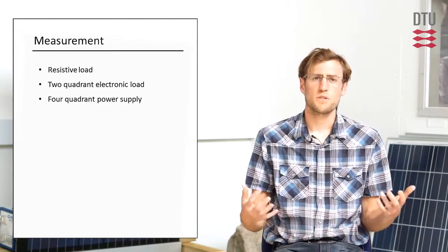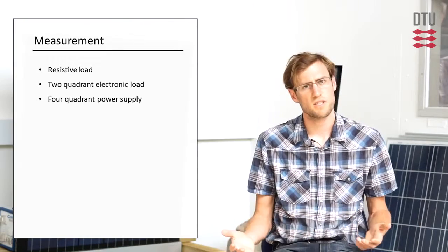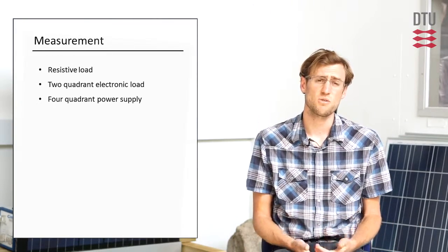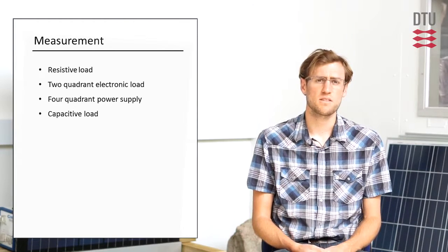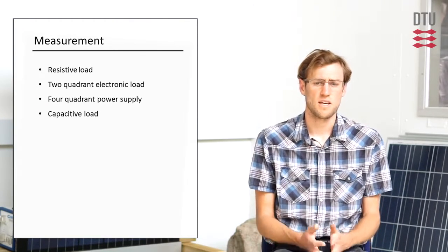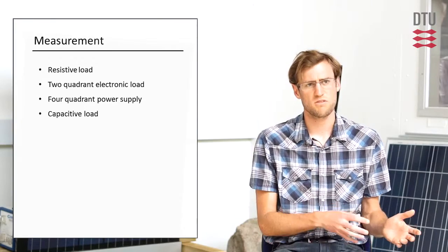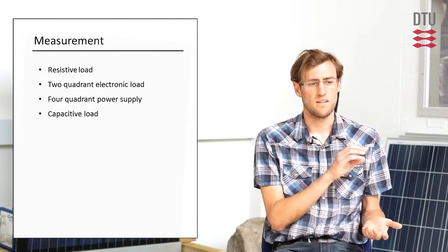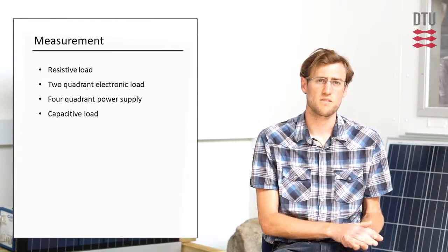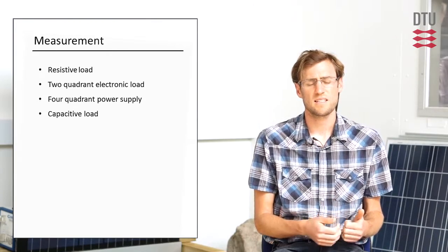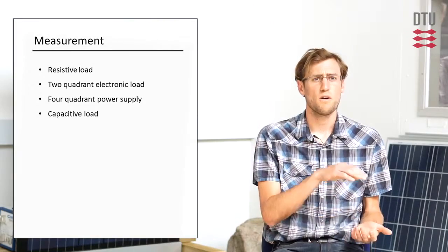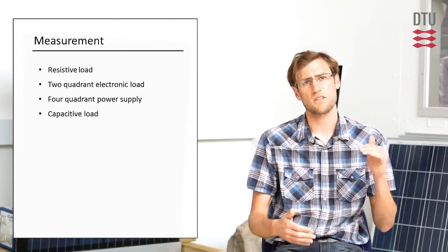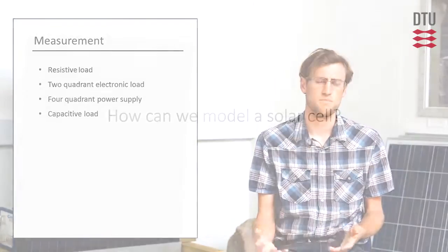In higher voltage strings, there's another set of options, one of which is to use a capacitive load. The capacitive load is essentially an array of capacitors, and when affixed to the PV device, we start in short circuit current, so the current spikes, and as the capacitor bank charges, voltage increases and current drops until we get to VOC.